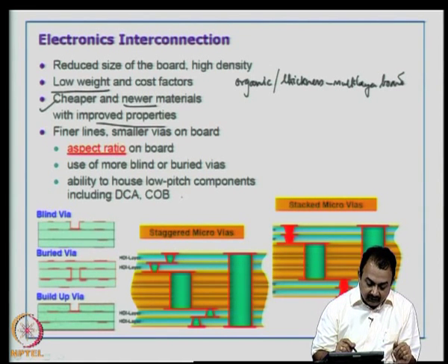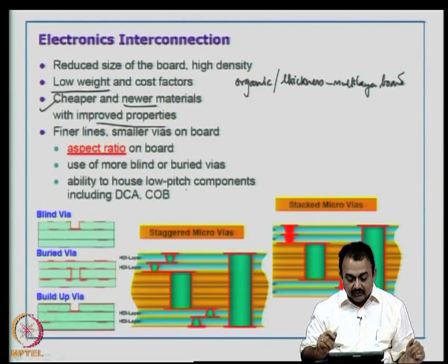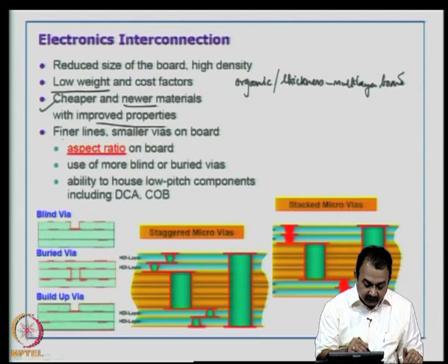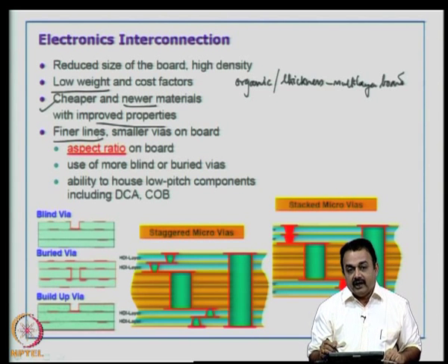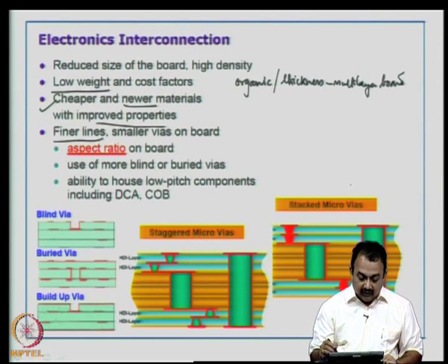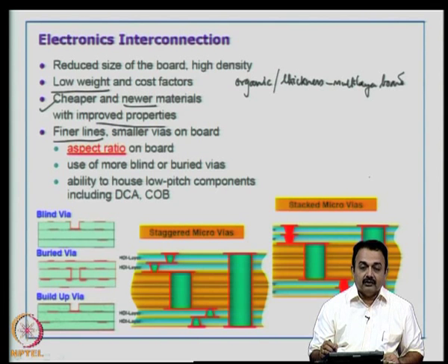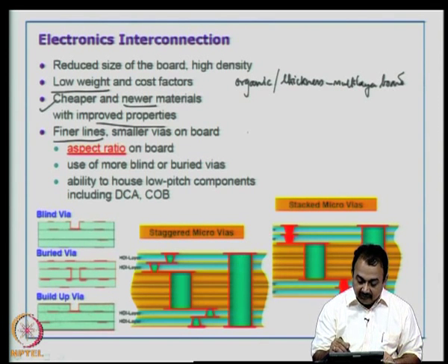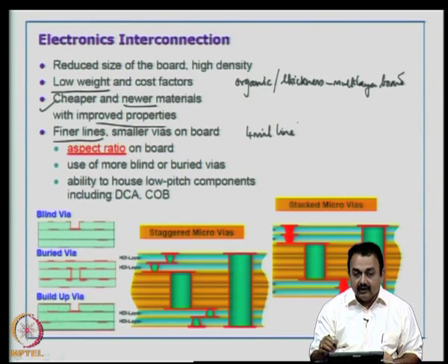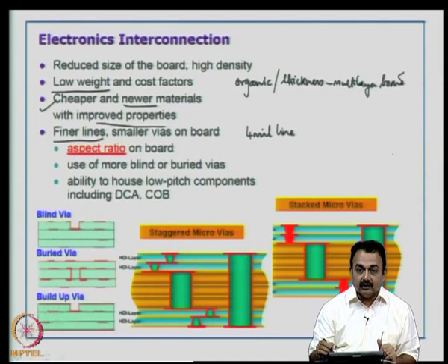As a manufacturer, you must be capable of having a line in your workshop to produce fine lines. So, if I say I am a manufacturer, and if somebody asks me what is your fine line capability, for example, if I say that I can do 4 mil lines, definitely I am on the leading edge in the market today.